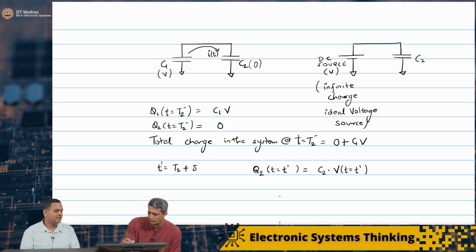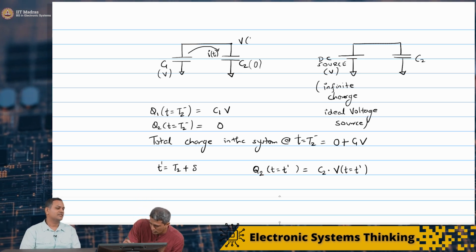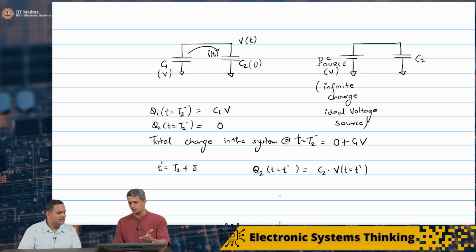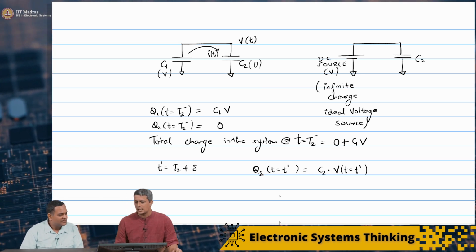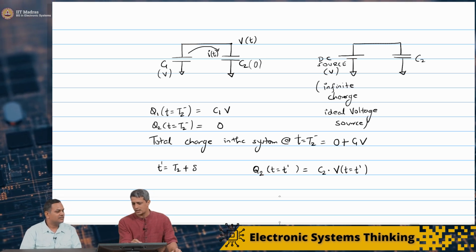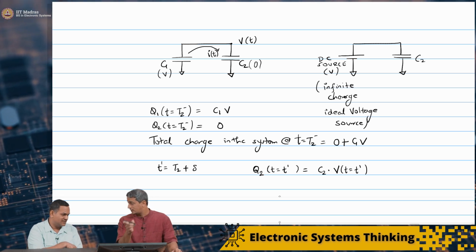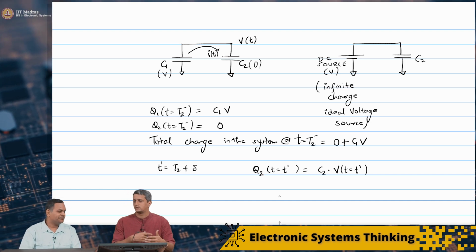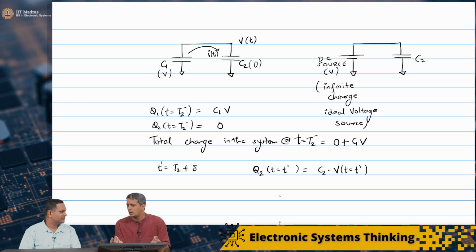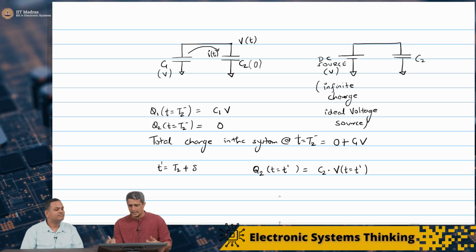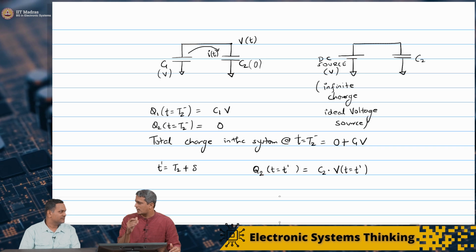Yes. Right. Okay. So if I look at the voltage here, V of t, and as you said, these two are the same for both. It has to change, and the same amount of charge has been lost by C1. Now you can have a current only if there is a potential difference. Yes. Right, and therefore eventually the current will stop.